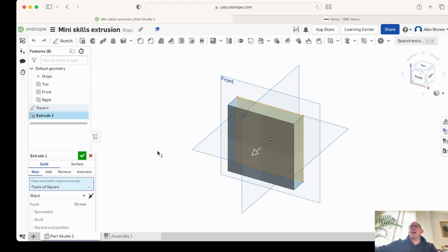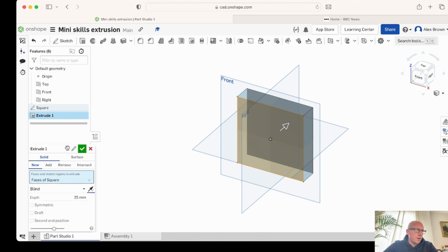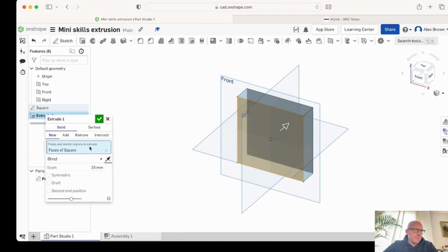That's extruding from the back forwards. It doesn't really matter. You can change that round if you click on that arrow there in the middle, or this arrow here, and it just flips which way it's going to extrude. You can also do various little bits and bobs, but for this all we need to do is change that figure there to 100, because we've made X and Z, and Y, the depth, needs to be 100mm as well, otherwise it's not a cube. So type 100, press enter.